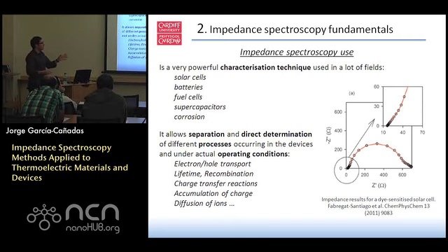So as you can see, again, from our impedance spectrum, we can quantify a lot of properties from our system. We can quantify Hall transport, electron lifetime, recombinations, diffusion of ions. So I guess the solar cell is a nonlinear device. But you use such a small amplitude that you don't have to worry about it? No. So what is the amplitude typically? Typically it's 10 millivolts, 10, 20 millivolts, 50 maximum.